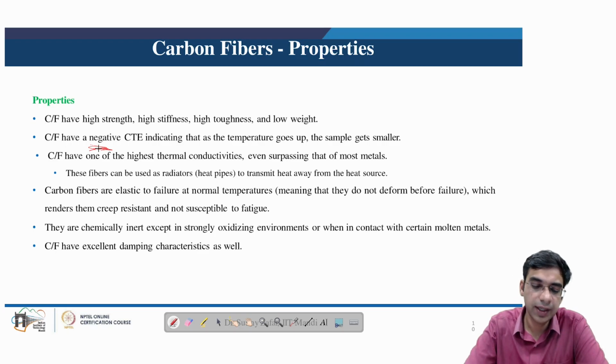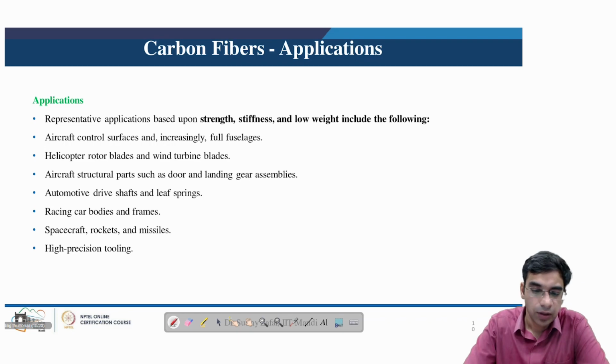which renders them creep resistant and not susceptible to fatigue. They are chemically inert in strong oxidizing environments, and they are also inert when in contact with certain molten materials. Carbon fibers are also known to have excellent damping characteristics. Because of this, not only in wind turbine blades, carbon fibers also find several applications in aircraft control structures, and increasingly the full fuselage of the aircraft may be made out of carbon fiber.